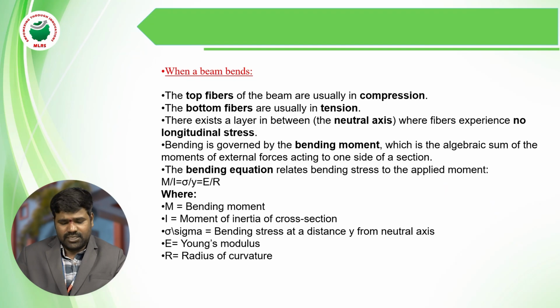When a beam bends, the top fibers of the beam are usually in compression, the bottom fibers are usually in tension. There exists a layer in between, the neutral axis, where fibers experience no longitudinal stresses.